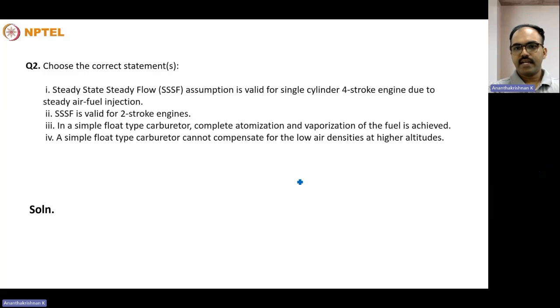So choose the correct statement. The first is, steady state, steady flow assumption is valid for a single cylinder 4-stroke engine due to steady air fuel injection. Second, the same steady state, steady flow is valid for 2-stroke engines. In a simple flow type carburetor, a complete atomization and vaporization of the fuel is achieved. A simple flow type carburetor cannot compensate for the low air densities at higher altitudes.